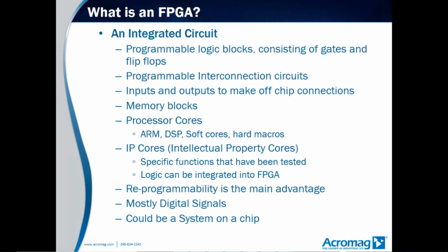So simply put, what is an FPGA? It's an integrated circuit that contains programmable logic blocks, and these consist of gates, flip-flops, lookup tables, memory blocks, and then you are able to take these logic blocks, configure them how they need to be, and interconnect them through a variety of ways on the FPGA. So these interconnections are programmable, and it allows you to customize to your requirements for your specific application.